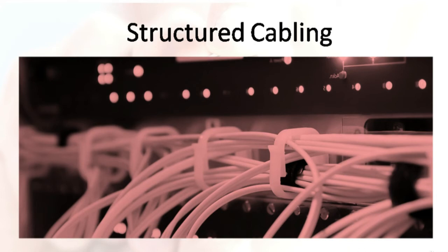Now, most of the cables of your facility will be residing indoors, but there will be cables residing outdoors as well, such as from the telecommunication demarcation point, which is usually off from a pedestal, to your building. These cables will need further requirements as they need to be outdoor rated. On top of the requirements of indoor cables, you will also need the cable to be water resistant, and in the case where the cable will be exposed to sunlight, it needs to be UV resistant as well.